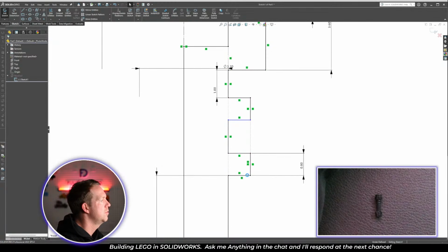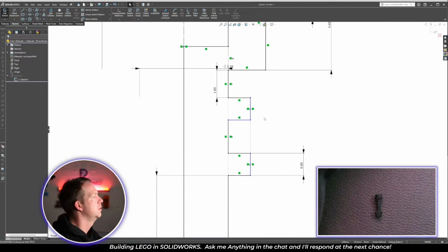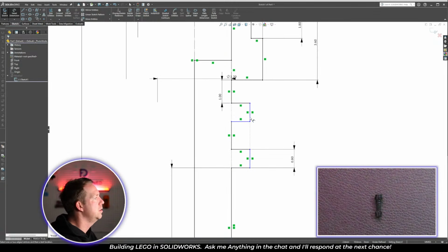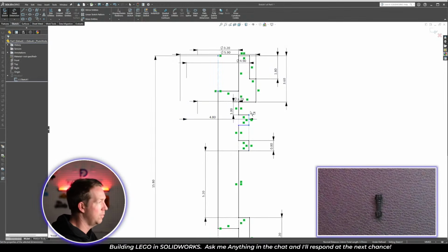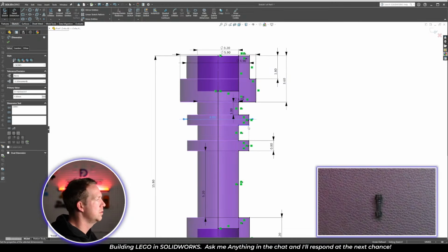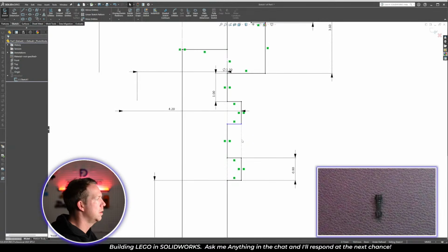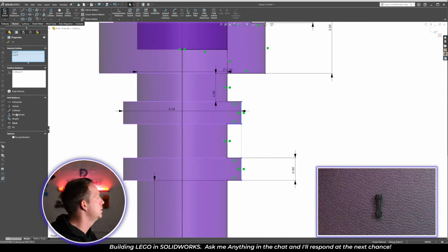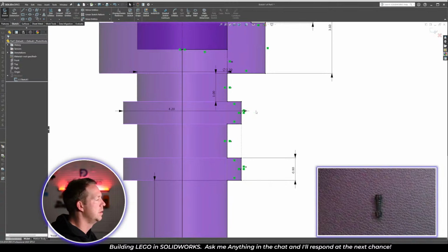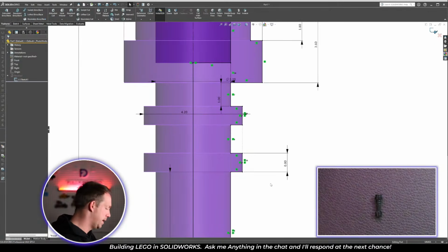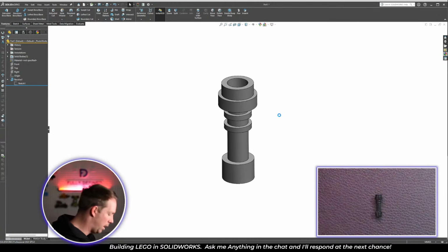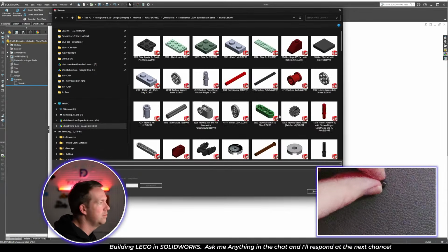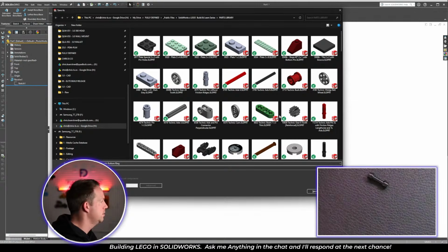So just remove a couple of those and use this one here. Put a new dimension in. So instead of 4.8, that becomes 4.2. I'll keep these two lines equal, which will keep the distance in between them the same. Now that looks better. All right, halfway there, or over halfway. Let's save the file.